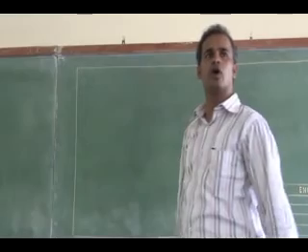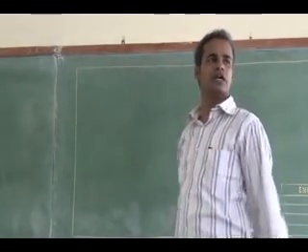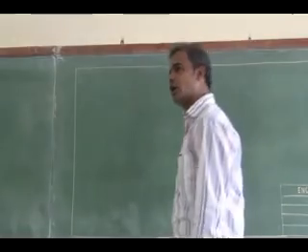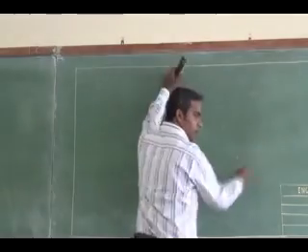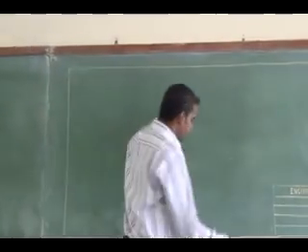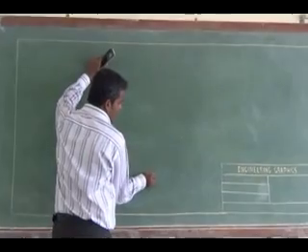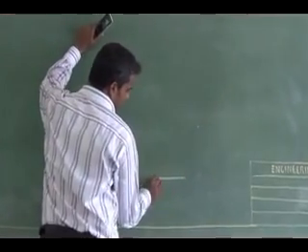The first problem is solved first. First of all, you have to draw a pentagon, as our intention is to get the involute curve for the pentagon. So draw a pentagon with a 2H pencil, keeping a side horizontal. How to draw a pentagon, you know it. Draw a pentagon of side 20 mm.